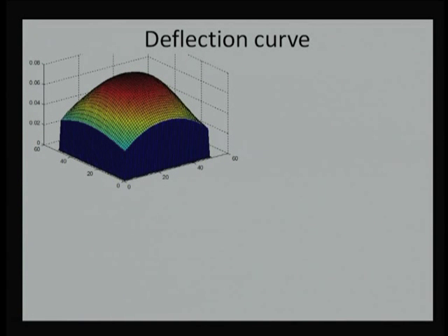Now, what will happen if I increase the film thickness at any point? Pressure is going to go down, and we really require an iterative loop to come up with the final results. What I am trying to say is: use the hydrodynamic lubrication mechanism, use that algorithm, and find out the pressure at every node.